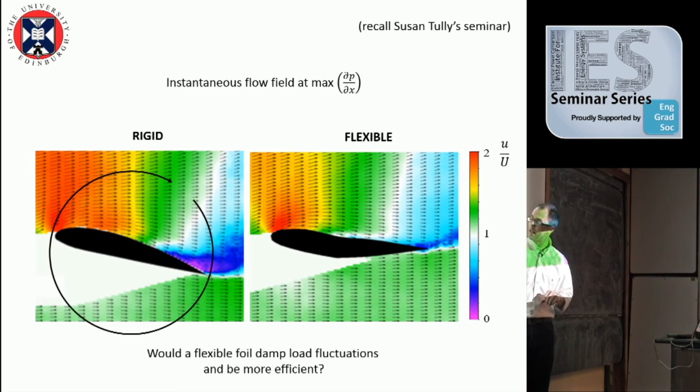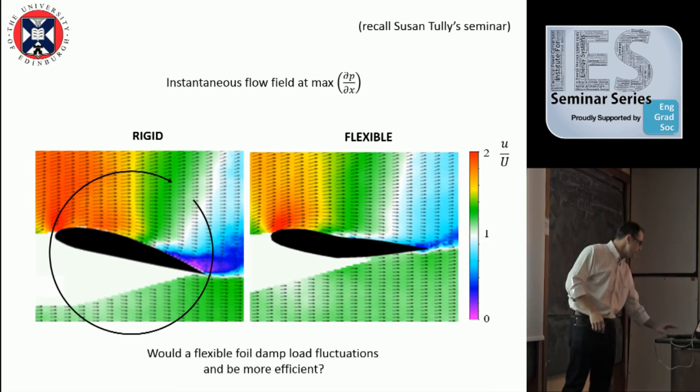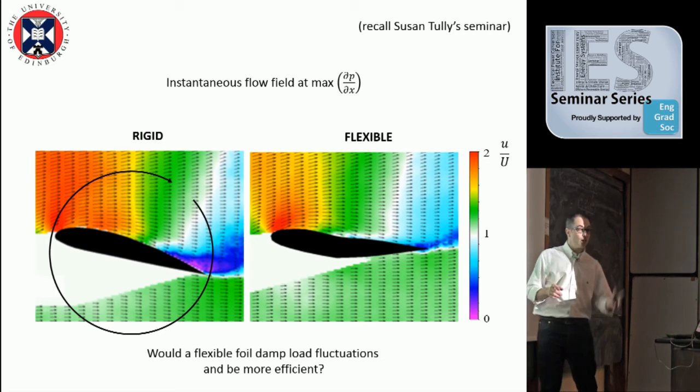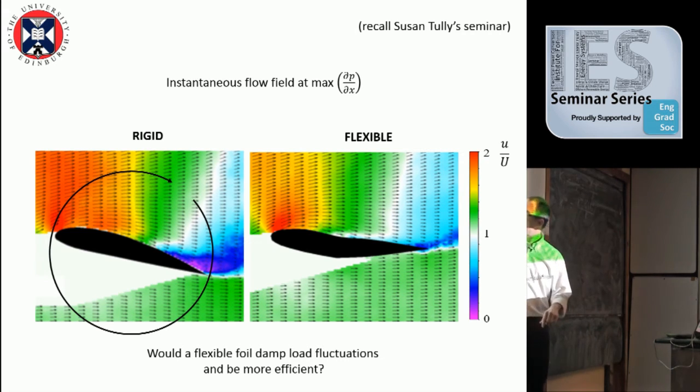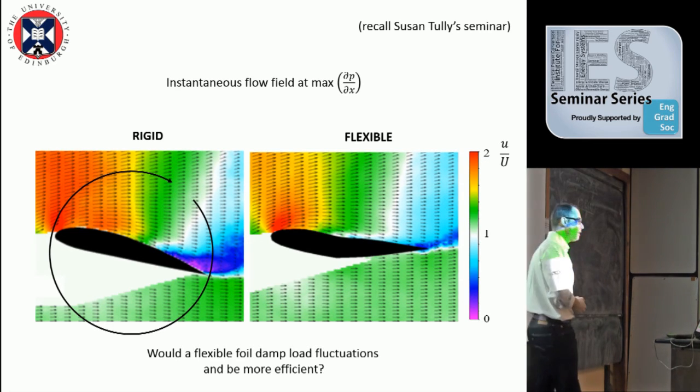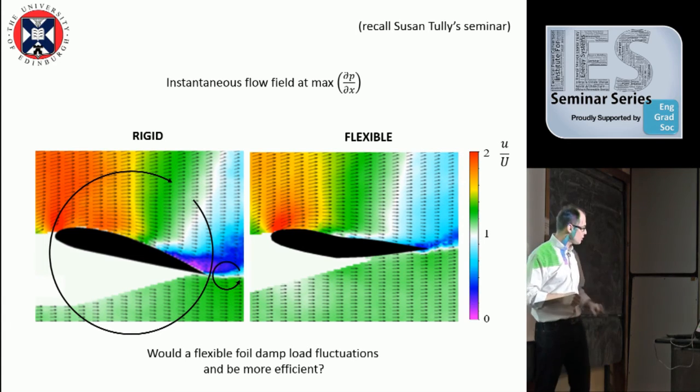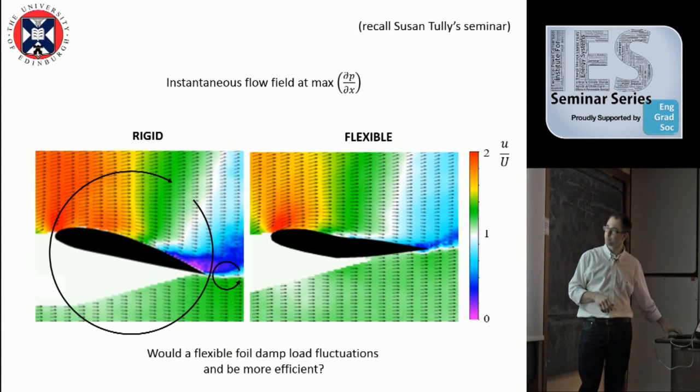So that means that actually here, you're now generating a vortex. Now, there are two vortices here that are playing a role. One is the circulation around the foil. So this big vortex, which you normally don't notice, but is the vortex that must be here in order to generate lift and to bring up the foil. This is the circulation. It's exactly the same as your lift. So there is a linear relation between the circulation and your lift.